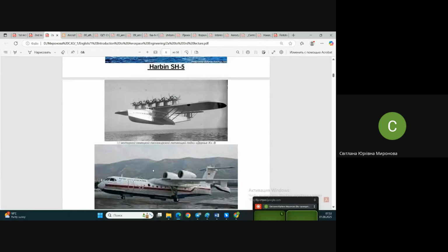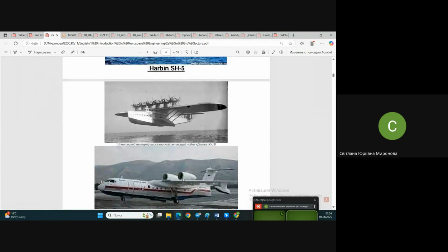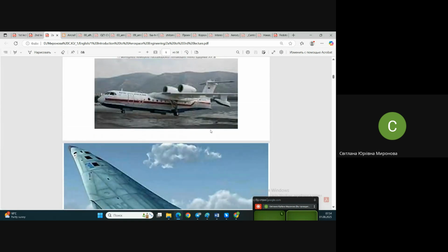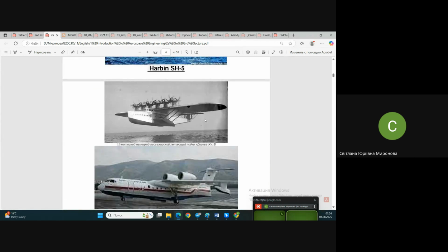And in this airplane, in a photo at least, it's not visible that it's really this type of fuselage, neither in front nor, no, not much visible. It's visible, but not much. Here is this change of shape, significant, typical. But what is common for both of these airplanes? This one floats under the wing. This one, you see, they are like screaming: I'm a flying boat. I'm an airplane designed to land and take off from water.